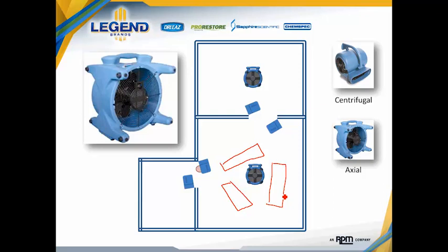Then the only thing that's left and remaining once this air movement strategy is deployed is if we do have moisture inside of walls or underneath cabinetry, etc., then we need to move to yet another category of air movement to ensure that we're getting airflow within those spaces. Either the base of the cabinets need to be opened so that the airflow from this air mover can move beneath those cabinets, or we need to use our specialty systems that force air or inject air within those spaces so that we can ensure again that our transportation system is addressing or affecting every one of those spaces where moisture and drying exist and need to occur.